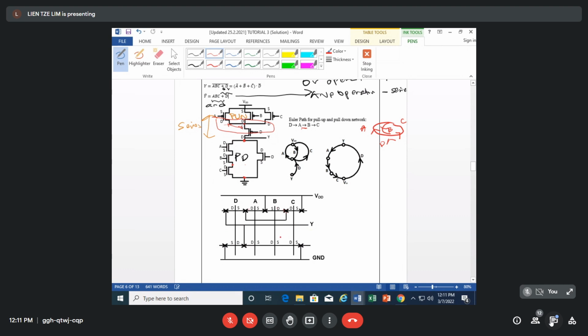So you see the pattern of the stick diagram in series and in parallel. Any transistors in series, you see here A, B, C, look like this. But if in parallel, the connections must use a contact to connect to each other.